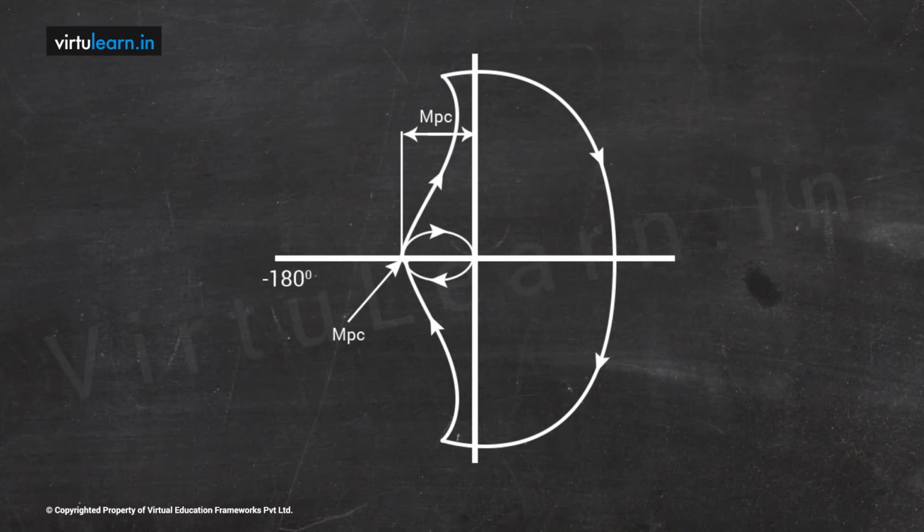Path 4's starting point is the ending point of the inverse polar plot. The ending point of path 4 is the starting point of the polar plot, so that the entire direction is continuous. So I can draw like this now. It is at plus pi by 2 and it is going through the right side, and because it's a clockwise direction, it is going back to here, the starting point of the polar plot, which is at pi by 2. So this is the complete Nyquist plot.